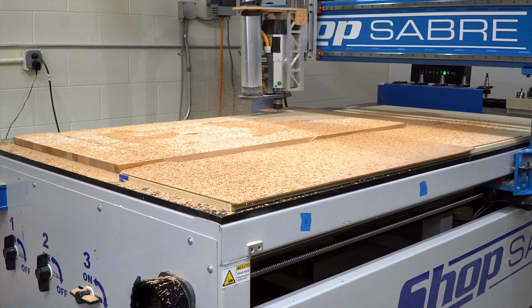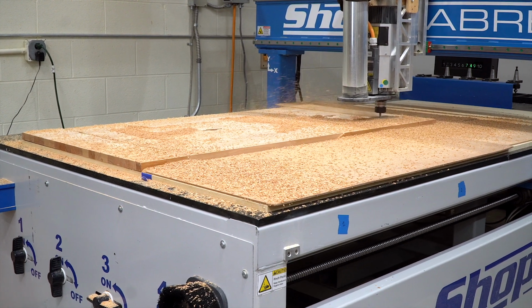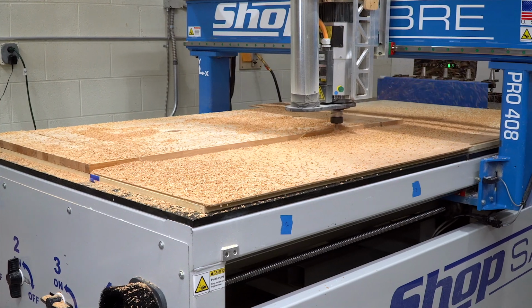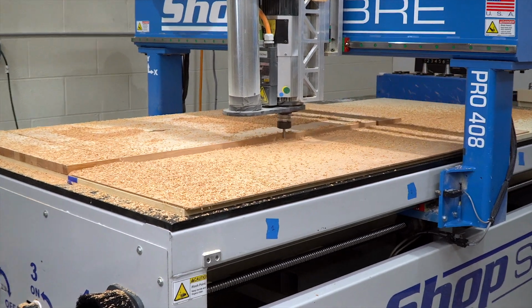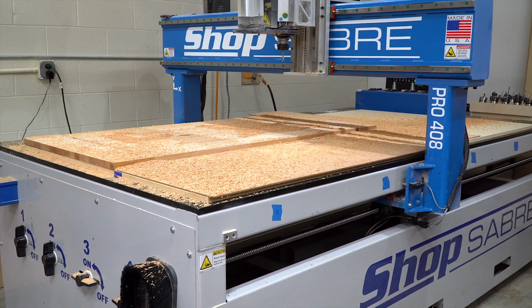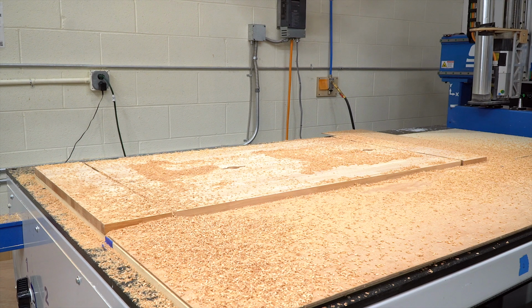And also it removes heat from the cut, like we talked about earlier, which helps extend tool life and you won't burn the tool or the material. It's just a lot better cut overall. The last thing that really helps with is it allows you to do a deeper cut because it reduces the strain on the spindle. So we did that whole 1.1 in just one pass.